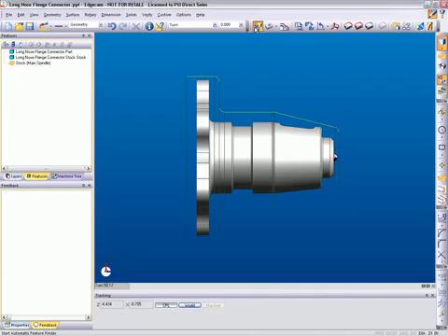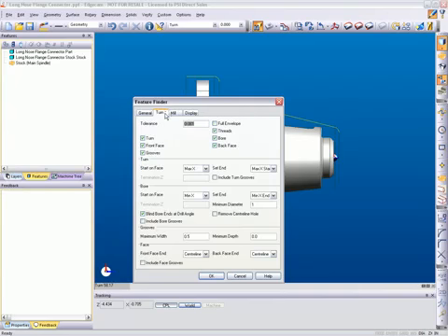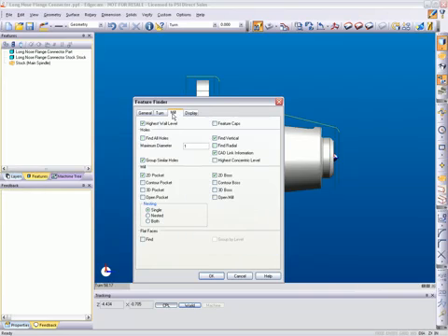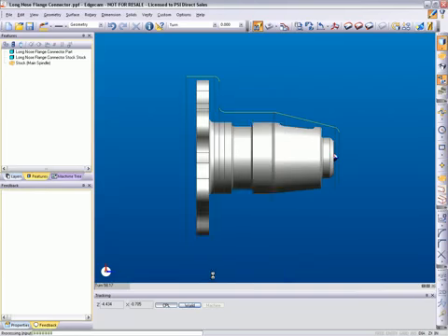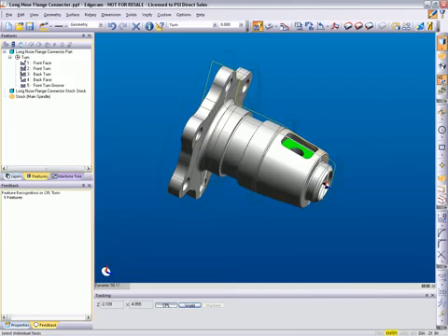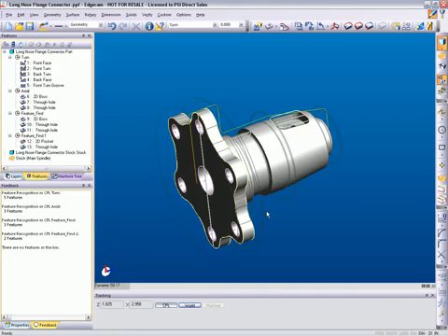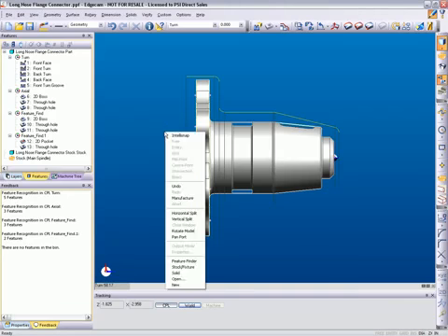The next step will be to feature find the component. We will digitize the model's faces to create work planes and features referenced from the created work planes. Move to the Turn tab and Mill tab to control which turning and mill features are created and how the model will define the features. Select the model, and then digitize the faces to which the mill features will be created for. Edgecam interrogates the model, and the manufacturing features are found.